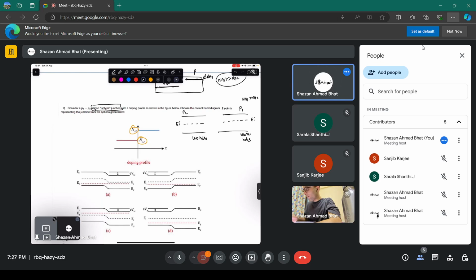As a result of this, the Fermi level is going to be much closer to the valence band in this case, and it will be slightly above the valence band in this case because there are fewer holes here. The closer the Fermi level is to the valence band, the more holes in that system. If it is closer to the conduction band, more electrons in that system. Just like that. So this is the Fermi level. Fermi level.